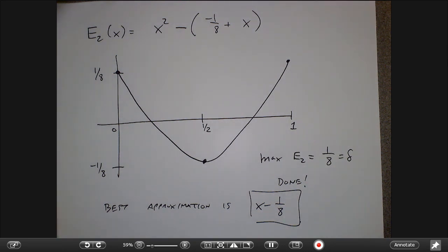Life is like that. Okay, so before I show you some Matlab examples to show you how this works, let me just stop and ask, does this iterative process always work? And the answer is kind of yes and no. Yes, in the sense that you can always get the Equiripple filter to converge on a set of extremal frequencies.